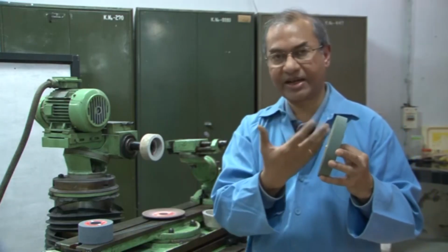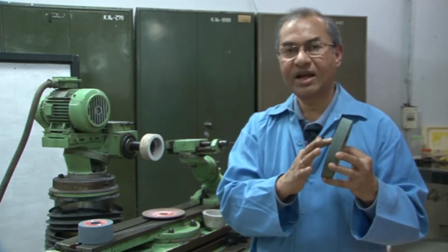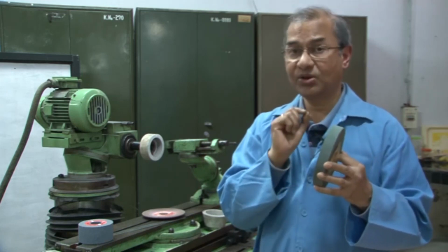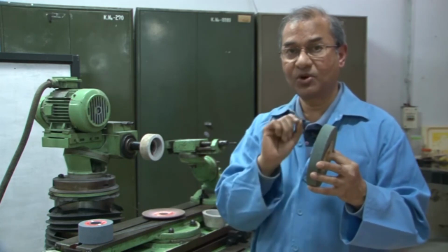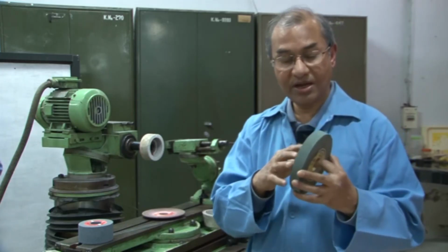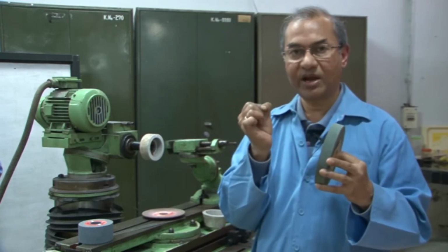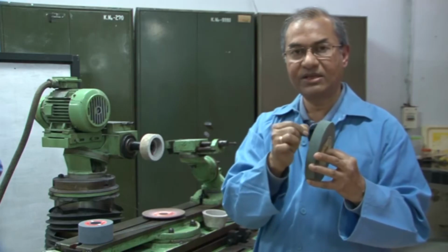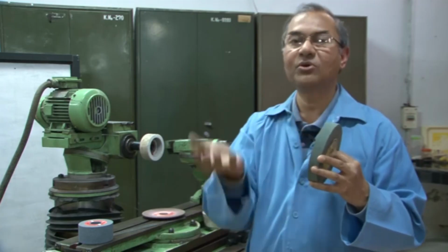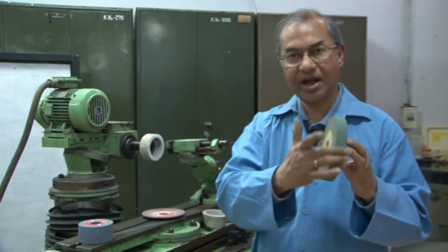Similarly, in the case of a grinding wheel also, in between the grains there is a space, and that space is actually given for accommodating the small chips, the chips which are very small anyway for the grinding process. Now, if those voids are very small, those chips will be staying in those voids and won't be able to come out. Then what will happen is that all along the surface of the grinding wheel,